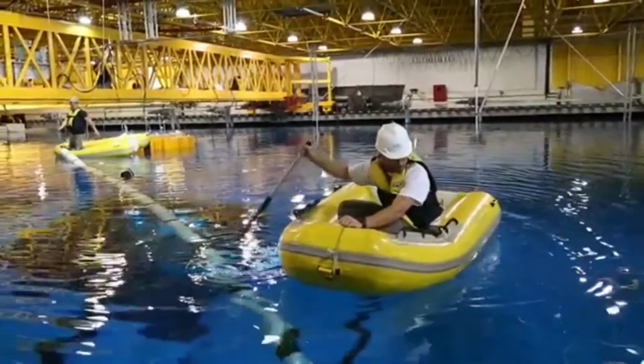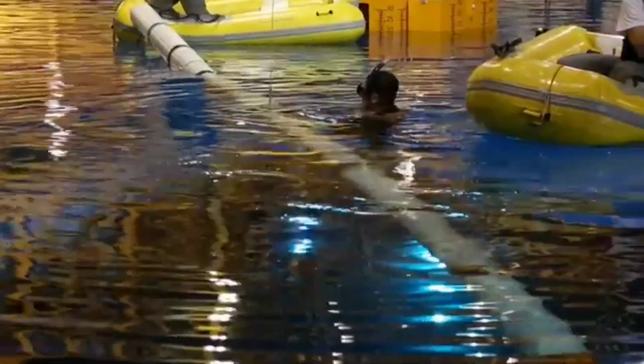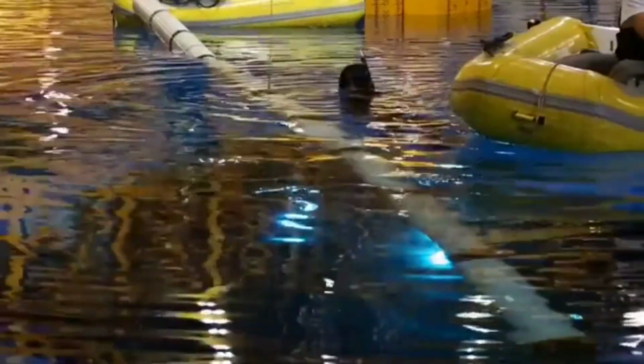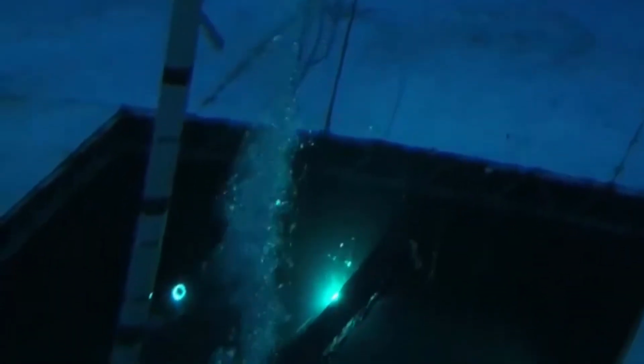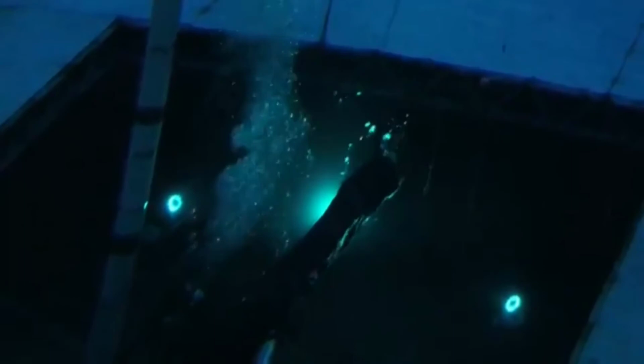The CWP is floated into the water, and divers install the 20-meter model in the Lab Oceano test basin. The depth at the bottom of the center pit is 25 meters, deep enough that the divers must decompress before emerging. Because so little is known about the behavior of the cold water pipe in the physical world, the loads, motions, and bending test data is invaluable.